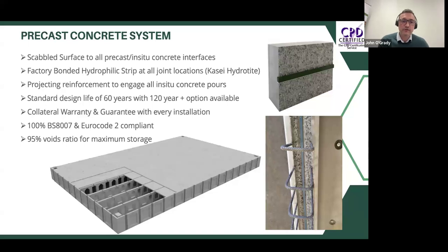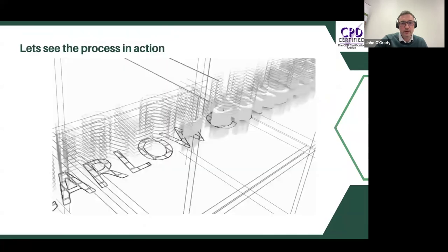The standard design life of a system like this is 60 years. That can increase to 120 plus. It depends on the project and the client and what they're looking for, and sometimes the water company themselves. So the voids ratio is 95%, which is not bad. So we're maxing out storage as much as possible.